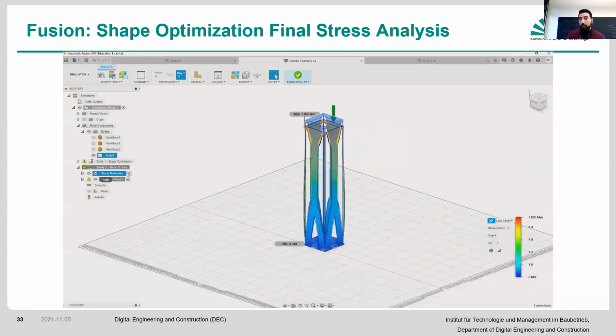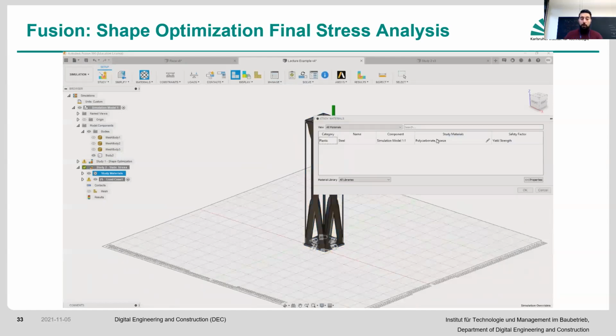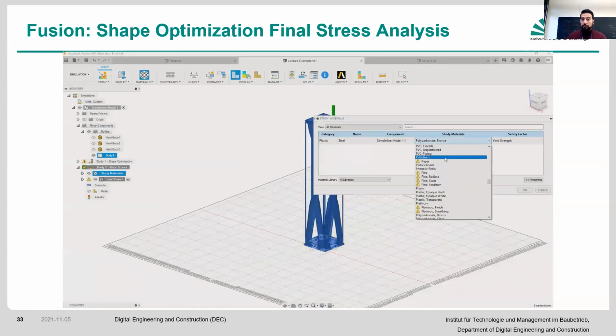What you can also take a look at, and this is a part of your term project, is instead of doing it from the materials library, I would like you to research how you would add a new material, and then go to the ASTM standard, go to other types of standards online, and see what material properties it actually has, and plug it in so that you can finalize the results.